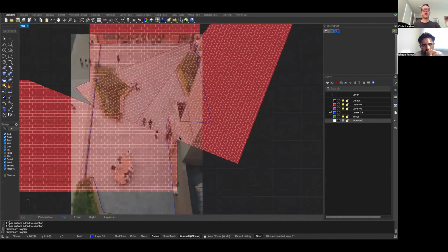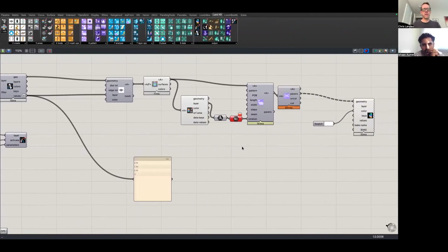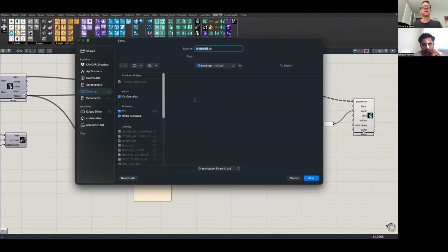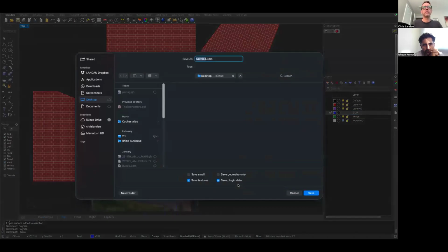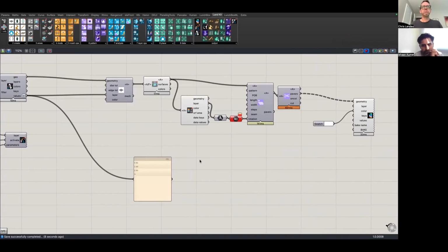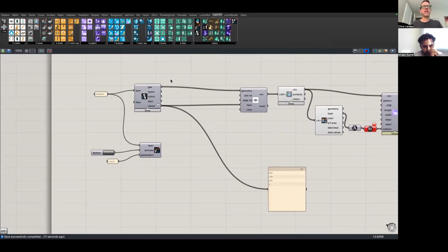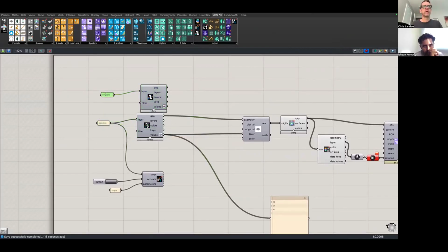This is not carefully drafted, but we'll call this limit of work or something, the clip. And then I'll go over here. Let me save these things. Call this paving. And then we'll save this. Call it paving, just for now. We'll rename them later. So we take the layer pipeline, we copy that, we change this to clip, and then the cool thing is that